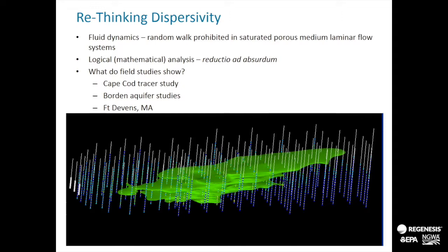We spent a lot of time trying to knock it down in the book, and probably the more sensible pathway was just to do what John Cherry does, and he says, okay, it's a process that may have some effect, but it's a very, very tiny marginal effect, so we really don't need to worry about it. And when it's carefully measured, transverse dispersivity is in the same range, same magnitude, as aqueous phase diffusion. And if that doesn't kill it, nothing will. So what we do find, though, is that we have at least the perception of longitudinal dispersivity, which is really French for heterogeneous advection.